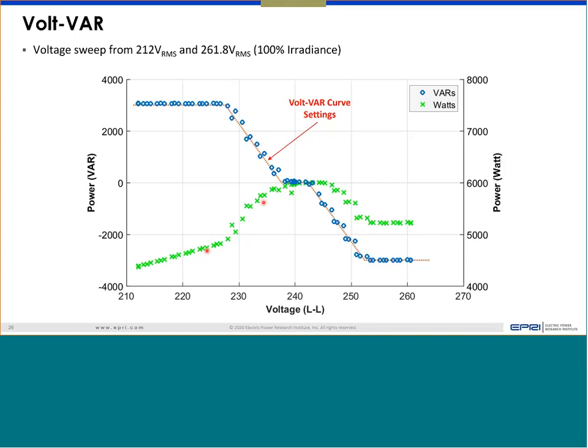power generation, or watt. So what we did in every case, we started from 240 volt and then went to, say, 242 volt and then brought it back, 250 volt, brought it back, 260 volt, brought it back. So we made a step change to go to high voltage, see what the inverter does, and then bring it back. Similarly, in the other direction, go to low voltage and then bring it back, and then calculated the real and reactive power from the inverter.